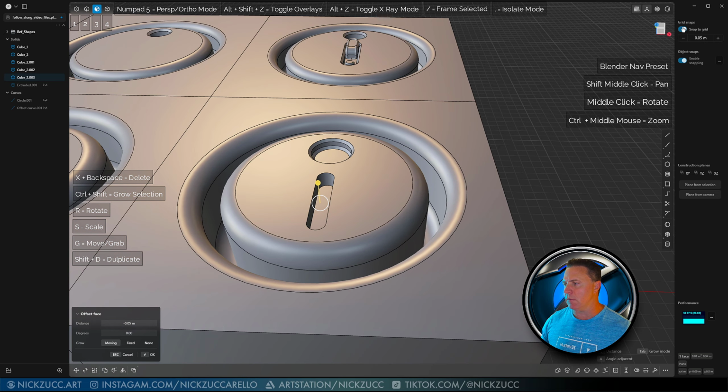I'm going to tap B just to make sure this is a new body because I'm dragging next to an already pre-existing body, and I just want to make sure that this makes a separate new part and a new piece. Okay. And then from there, I'm going to take the sphere. I'm going to drag out from the center like this, and I'm just going to tap B for new body and make something about this size like this.